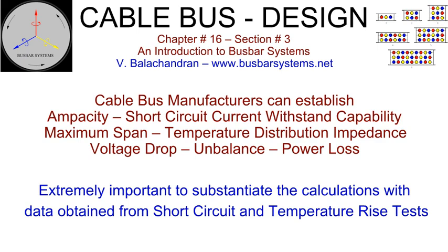Voltage unbalance. The above parameters will depend upon the phase-specific matrix of conductors and therefore can be optimized for the most favorable configuration. The capacitance of the low-voltage cable bus may be neglected. Medium voltage cables have shields and hence their capacitance to the ground will be independent of the configurations.